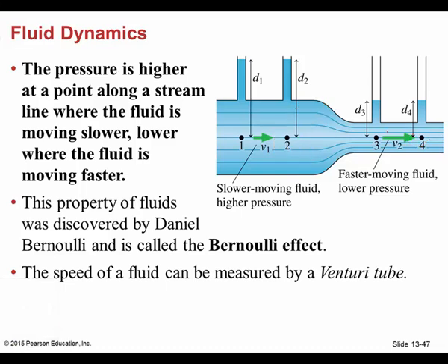And so what happens is you create an area of low pressure, like a vacuum. It causes suction. Now this process is called the Bernoulli effect. Anytime you have a fluid moving through a large tube, where it's moving slower, you have high pressure. Where it's moving faster, you have low pressure. Much narrower opening. We also get into what's called the Venturi effect when we look at carburetors on lawnmowers and cars with the old carburetor systems. It worked on the same principle.